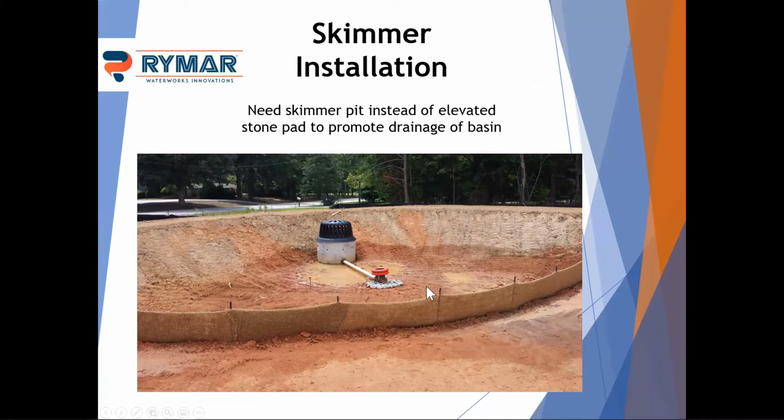What happened, the contractor graded this. They looked like they did a pretty good job. They tracked the slopes. It hadn't been seeded and matted yet, but that's probably coming. They've got their baffles in, which is good. They've keyed those in. But then they installed the stone for the skimmer on top of the graded area. And as you can see, it's already rained once, and you've got permanent ponding, or relatively permanent. It may infiltrate, but this looks like a pretty clay red soil, so likely to hold there.